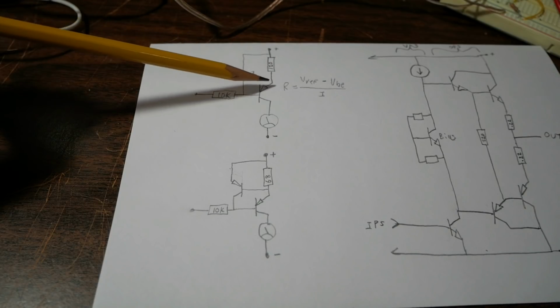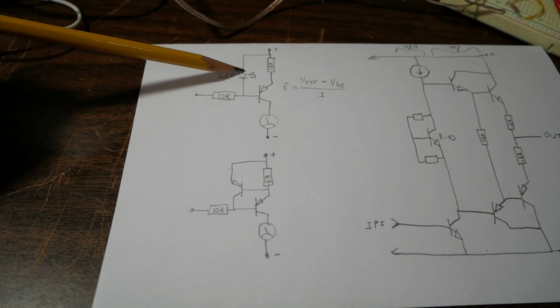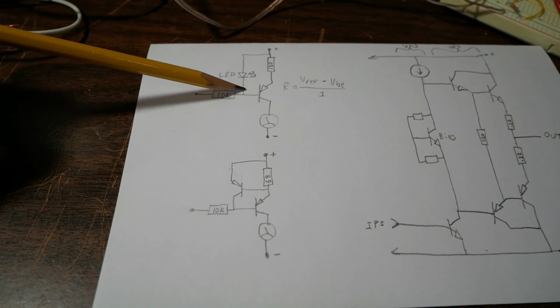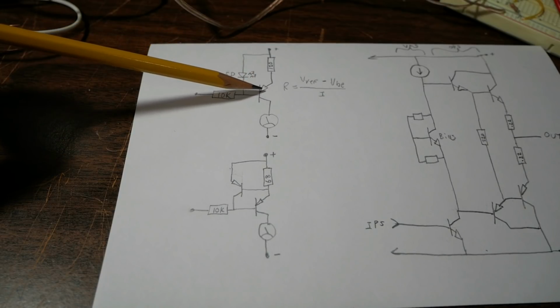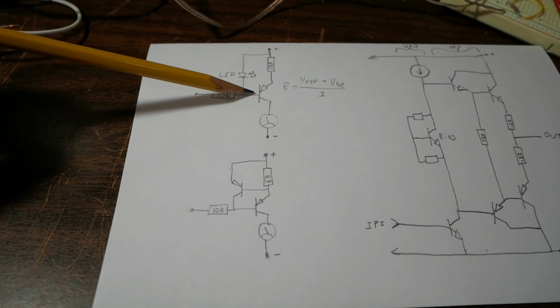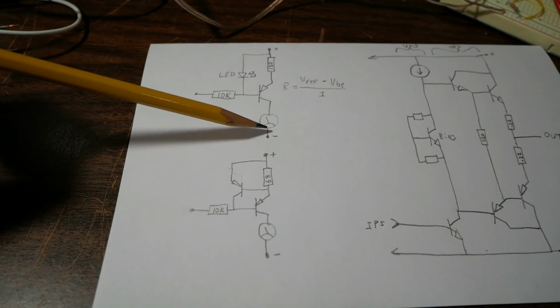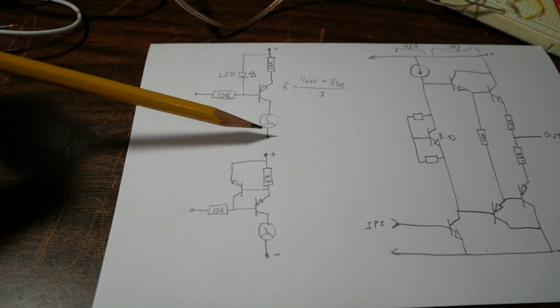When you increase the voltage drop, more current is going to shunt through this circuit, because remember, this is a voltage reference. It wants to keep this voltage set at a certain level. So if you increase the voltage across it, it's going to conduct more and shunt current away from this transistor, so less current is flowing through the base. So it's going to decrease the current flowing through here and bring it back into spec. And the converse is true as well.